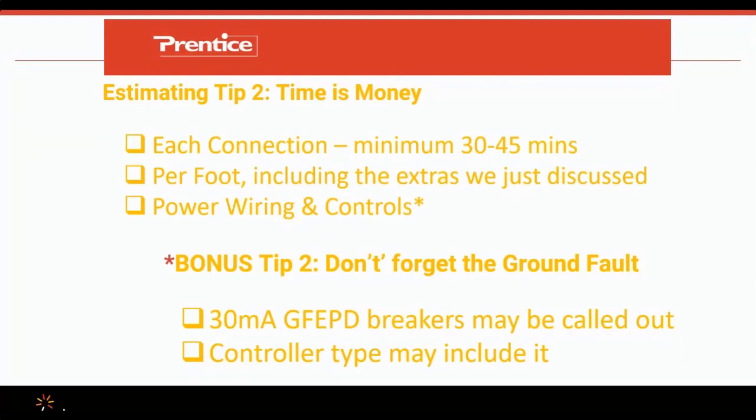You can have a 30 milliamp ground fault equipment protection style breaker, or you can have the controller itself have ground fault protection included in it. So be sure to think about that. And if you have any questions, be sure to ask us and we can get you through that.